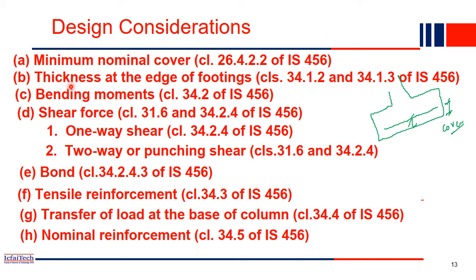Now the third consideration is calculation of bending moment and shear force, because in a foundation also the load may come directly as axial load. If the load is axial load, then there won't be any bending moment. But if the loads are coming in an eccentric manner, in that case the foundation may also be subjected to bending moment.